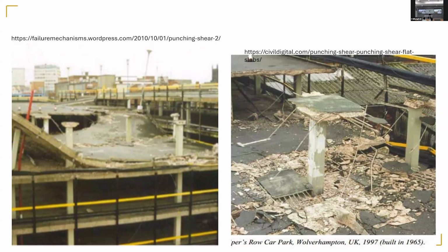So what happened in my project was that this is one slab, this is another slab, columns here, another slab, and foundations. They were going to cast this slab, so they put all of the formwork on the slab below. And then they also stored the material, like cement bags and things to mix the concrete, because mixing is done by hand. There was no delivery of concrete at that time. So they said, okay, we don't need to put the concrete here, why don't we mix here and then take it? And they put all of the concrete mixing and the material, plus the weight of this slab, on top of this slab, and they did not brace this further.